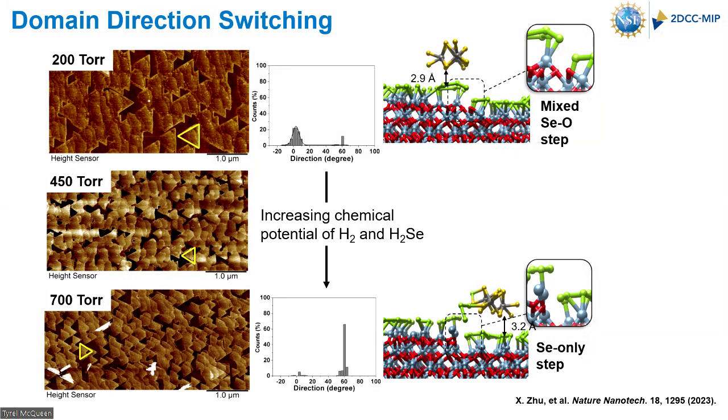And that's going to change depending on the particular deposition method you're using, if you're using MBE or MOCVD, but also the conditions you're using, because that's going to change the extent of hydroxyl group removal and chalcogen passivation. So bottom line, there's a lot going on there, right?